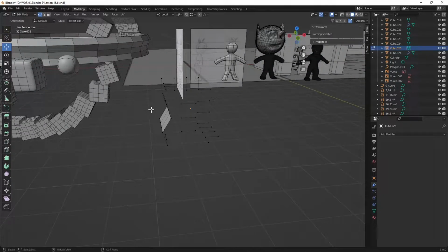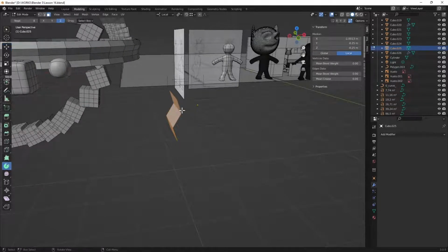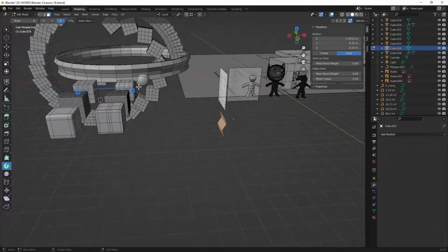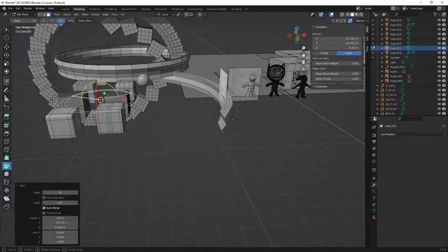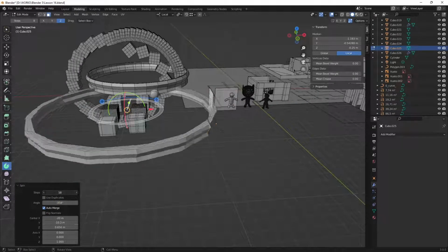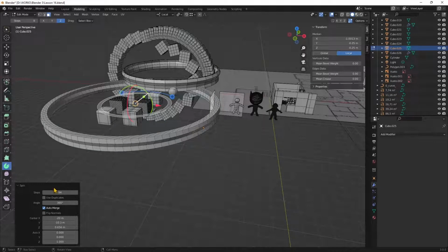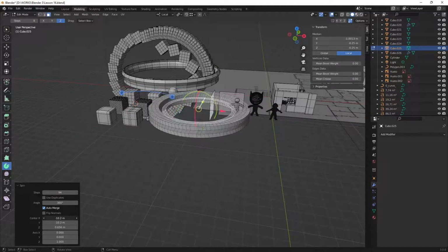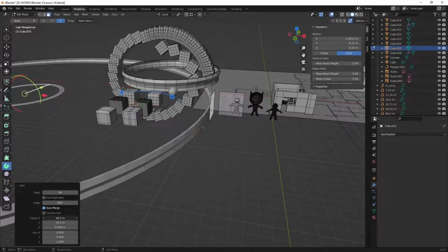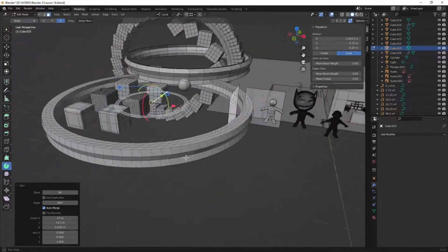And then when you do that, you can select the faces, and you can do the spin. Okay, so it works similar to the array. So you always have that gizmo, but if you click here, again, what you're creating is a revolving shape. So you can increase the steps if you want more subdivisions, and also you can set the correct angle here, 360 to close it up, and then you can change the center from here. So you can create wheels or, well, anything, vases or dishes, anything that's again kind of a circular shape.